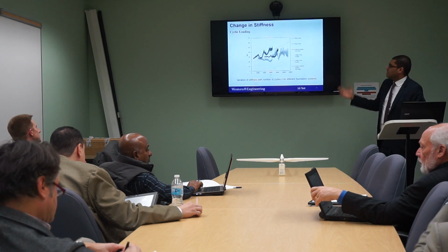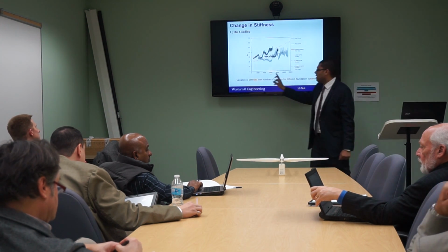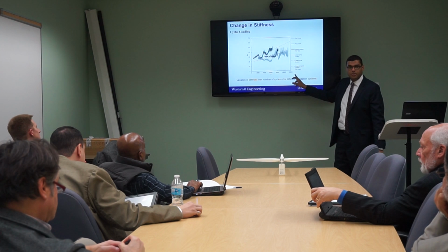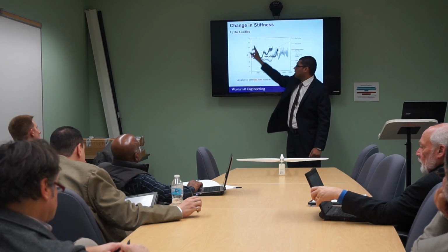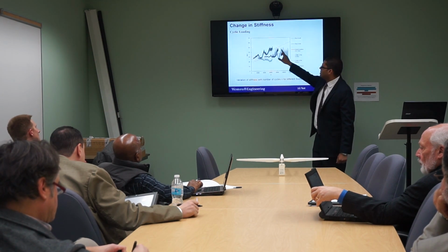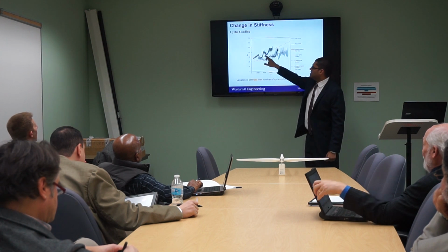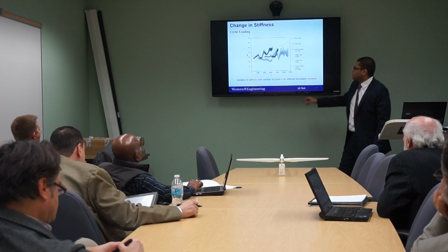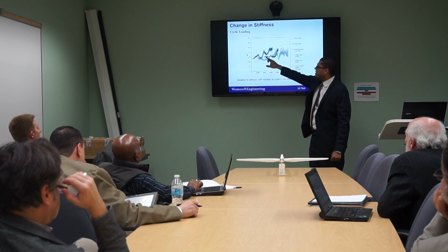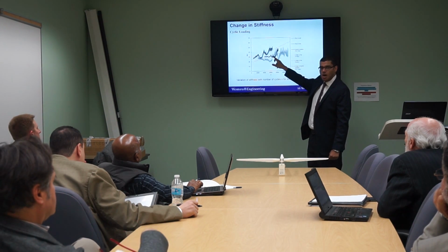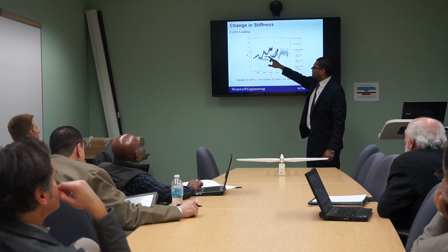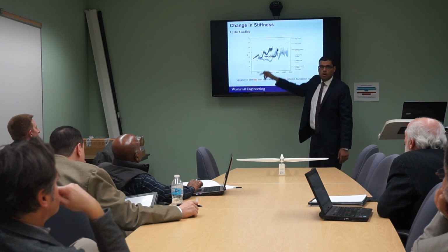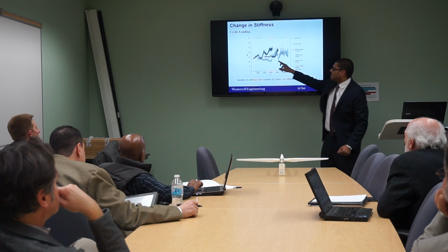We already studied the effect of several number of cycles, up to 12,000 cycles, on the stiffness of different foundation systems: 4 meter diameter, 6 meter diameter, and hybrid system. And we can see here with different number of cycles that the change in stiffness in the hybrid foundation system is, we can say, constant or steady. So this is the effect of the plate.